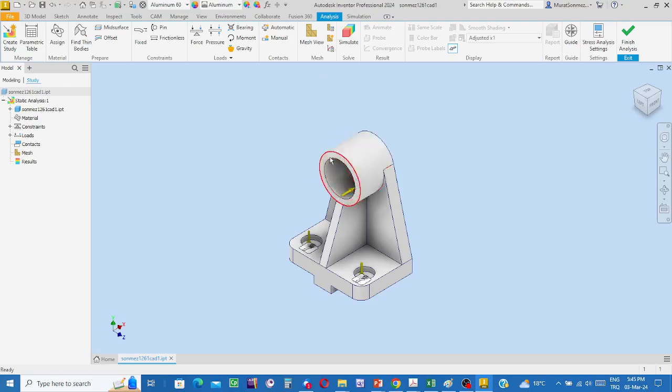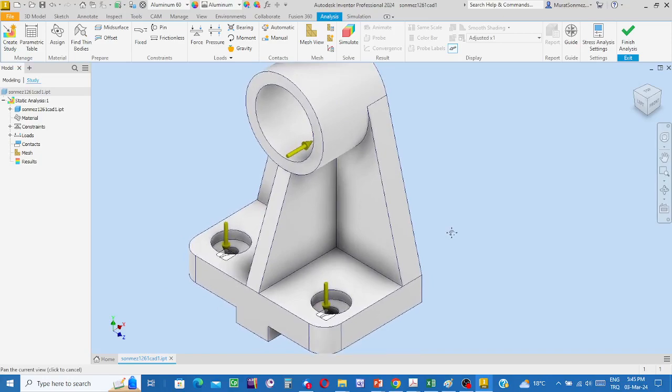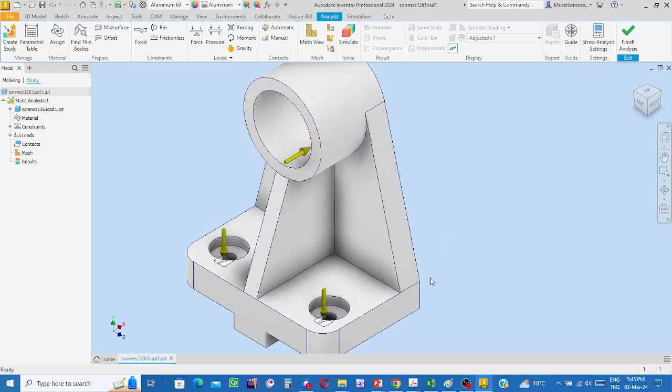In following lectures and the corresponding video records, I'm going to say that there is a sharp directional change. To decrease the stress value in the vicinity of a sharp change, use rounds, fillets. And also, to find the stress value more accurately where the geometry is not uniform but changing, use smaller sized finite elements at such places to increase the accuracy of the calculation. But here, I'm going to use the default configuration of the software,